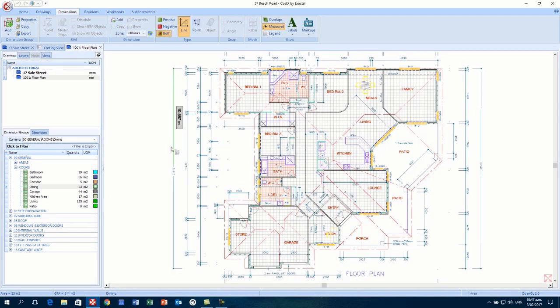And you'll see that this is actually a DWG CAD file. One of the first things that you'll probably notice is when I move the mouse cursor over onto the drawing, the mouse cursor actually sticks to the lines. So that was that intelligence that I mentioned previously. There's a lot more intelligence behind a file type like this, and therefore it's beneficial to measure from a file type like this. Very similar to a vector PDF file, a couple differences which I'll get to in a second. The first one is layers.